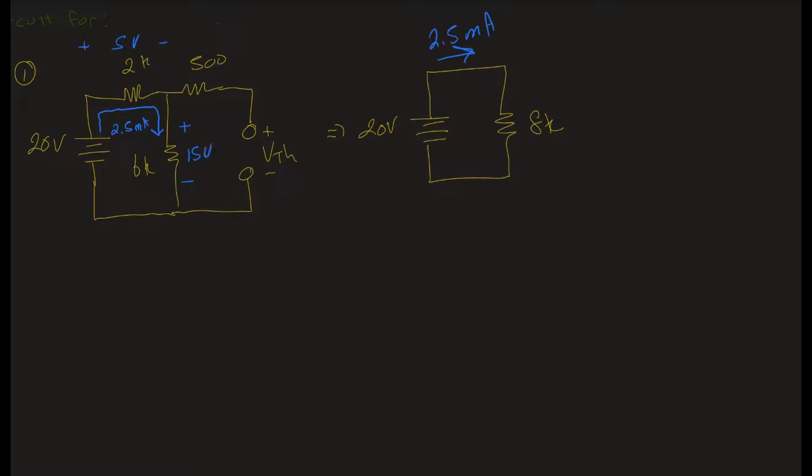So 15 volts. And again, remember, this is our ground. And so again, we just need to get the difference between here and here. If this is connected to ground, so it's 0 volts on this side. Notice if it's 20 volts, and we go down by 5 from here to here, this bump must be at 15 volts. And again, that makes sense, because notice if I started here and we're at 0, and I go up by 15, then that shows me, yes, I did this correctly, I'm at 15. The part I wanted to make sure is, what is the voltage here?